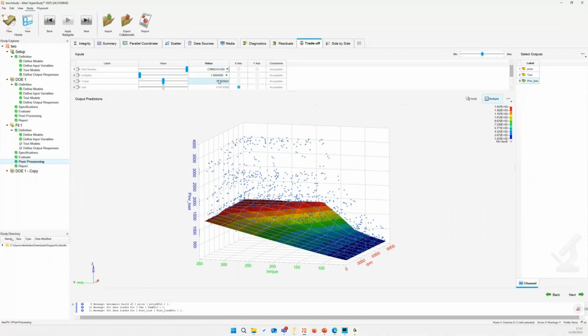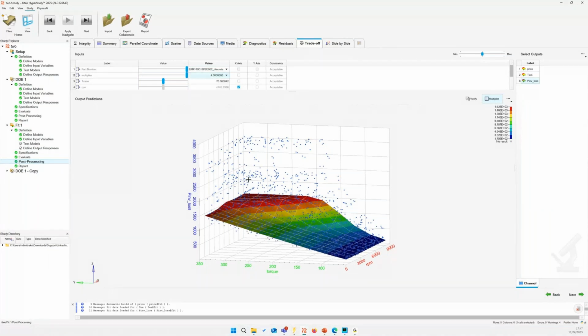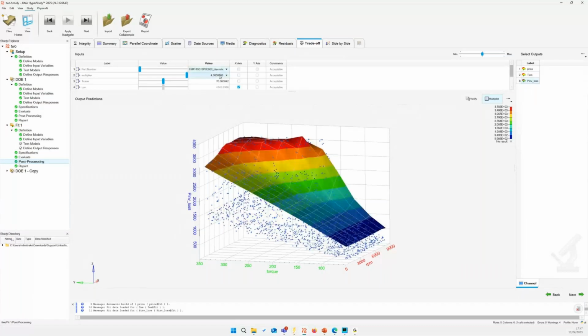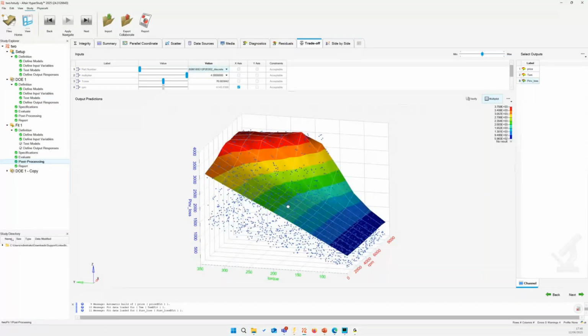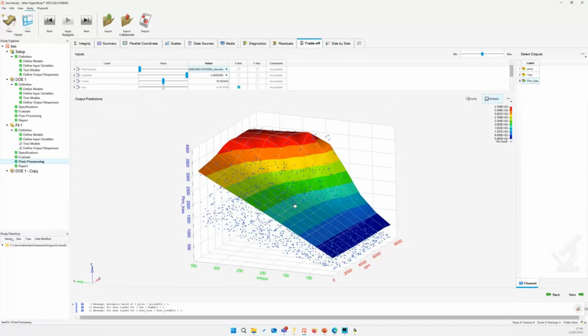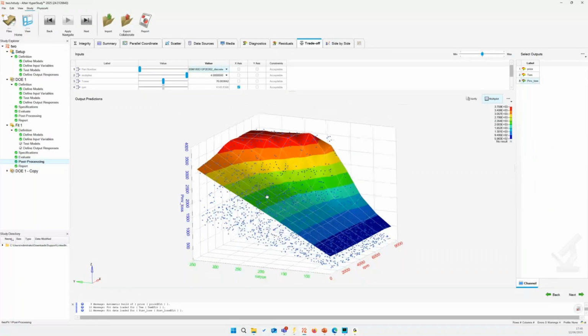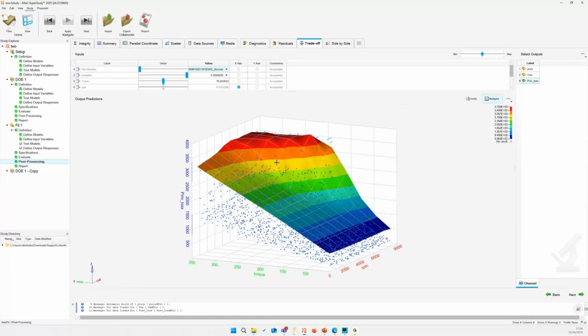You can change, for example, the gate resistance, and you can see the effects. I can change the semiconductor. Oh, I see a big effect here. So this is very nice to visualize the design space and the different options you have for the market as well. And the cool thing, which couples with these multi-level efficiency maps, is the fact that you can apply this in the 1D space to have WLTP cycle simulations that run extremely fast.